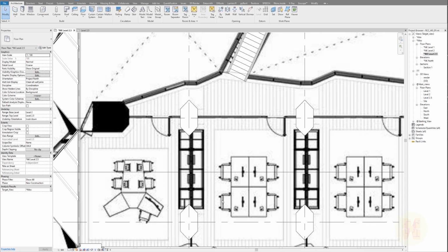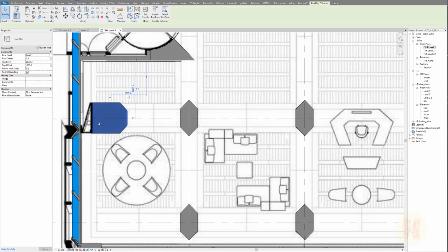So now it's time to talk about the walls. You can see here some columns. If you remember, we have the same column on level 1, and I recommend you just copy it to level 2, to level 3, and on and on. But here we have one thing: this column is going from the first level to the second one. This is right, this is one huge column, but we also have the extra level 2.5, and after that goes level 3. Better I show you in 3D.